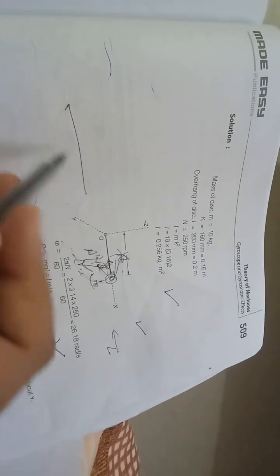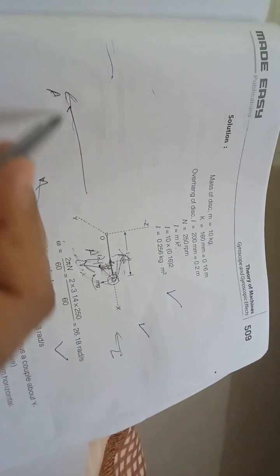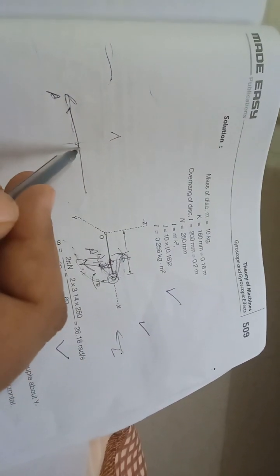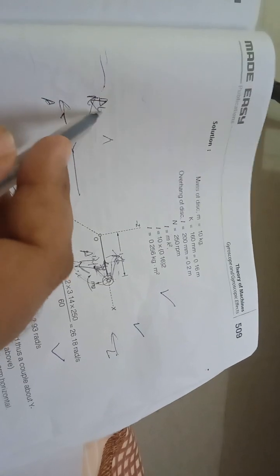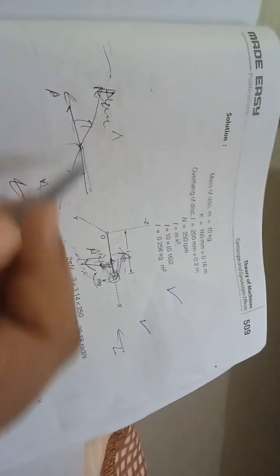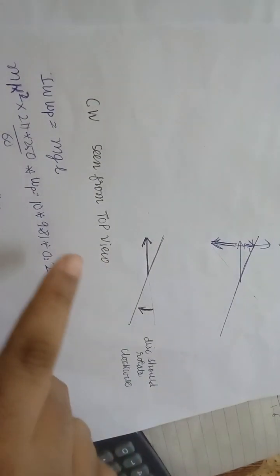I think you have not understood what I'm trying to explain. This is the shaft, L is here, you need a reactive torque here, so the action torque with this direction means you need L new in this direction. L new is this direction, meaning this has to go here. What is this motion? This is clockwise, so the shaft has to rotate clockwise to counter the clockwise, as seen from the top. The disc should rotate clockwise. So yeah, this I verified.